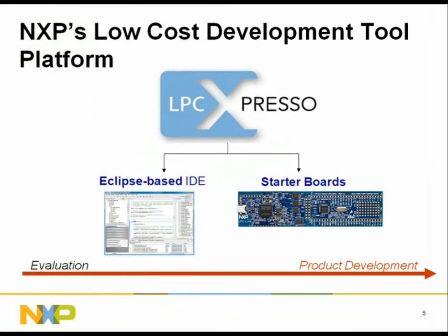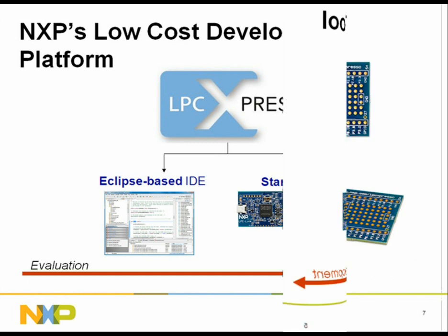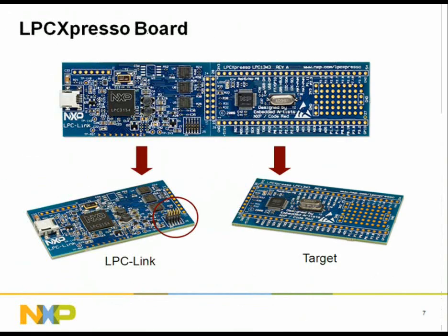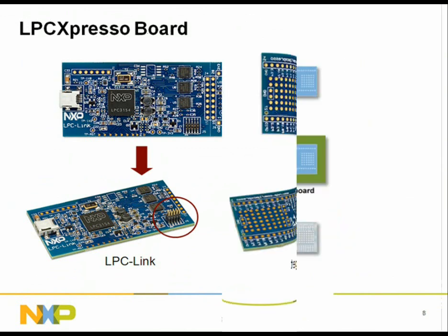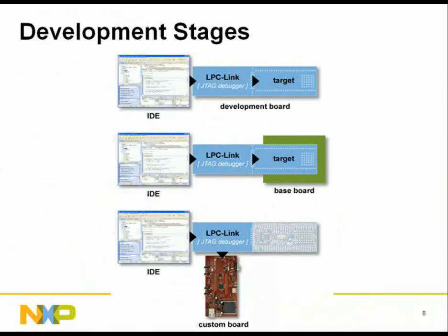LPCXpresso is a new low-cost development platform available from NXP. The software consists of an enhanced Eclipse-based IDE, a GNU C compiler, linker, libraries, and an enhanced GDB debugger. The hardware consists of the LPCXpresso development board, which has an LPC link debug interface and an LPC ARM-based microcontroller target. LPCXpresso is an end-to-end solution enabling embedded engineers to develop their applications from initial evaluation to final production.